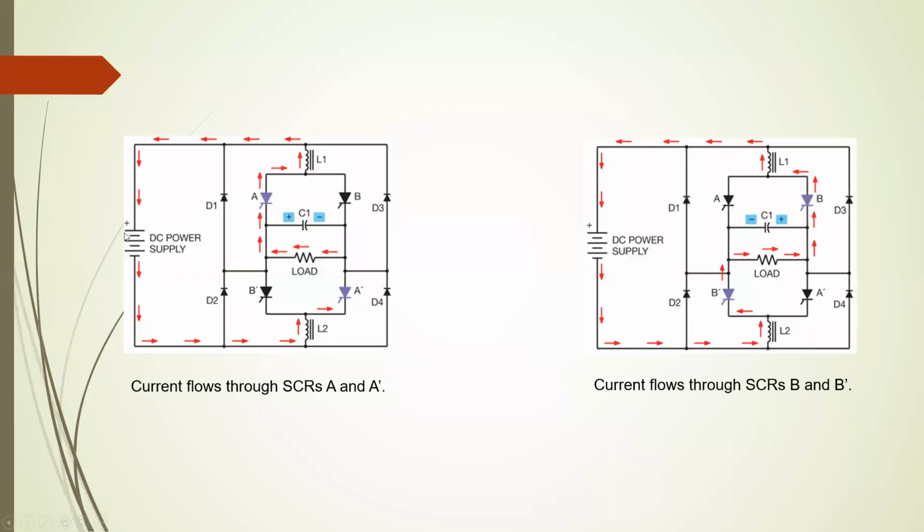Here's the DC supply portion from the variable frequency drive, and here we've got our kickback diodes for the changing frequency. When we turn this on, SCRs or IGBTs or BJTs, A and A prime turn on first. So here we have our path coming in, and it's going this way through the coil and leaving.